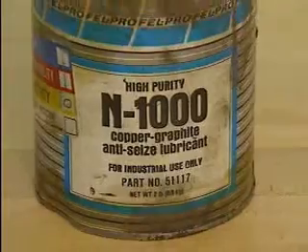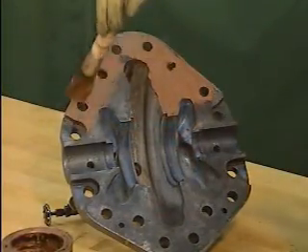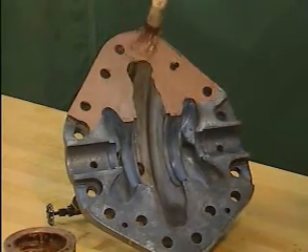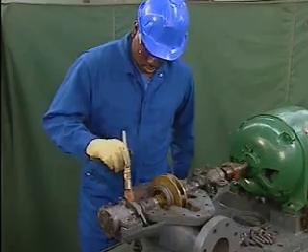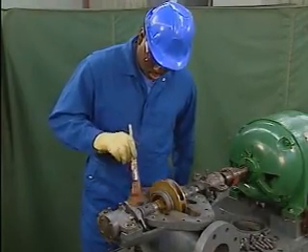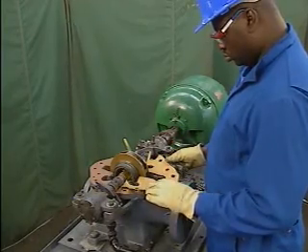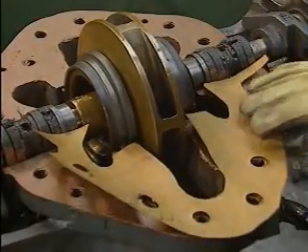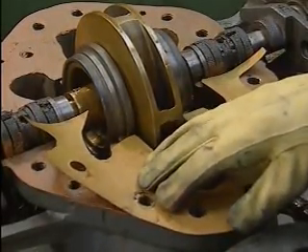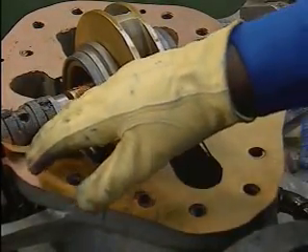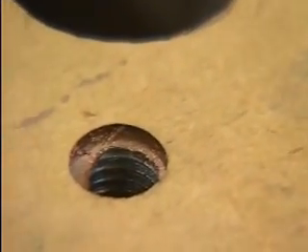The manual for this pump recommends using an anti-seize compound. After removing the bluing substance from the casing, the mechanic applies the anti-seize compound to the sealing surface. He applies the compound to the lower half of the pump casing as well. The mechanic then places the gasket halves on the sealing surfaces of the lower half of the casing. He carefully lines up the gaskets with the edge of the pump casing and checks to make sure that all the bolt holes in the gaskets are properly aligned with the bolt holes in the casing.